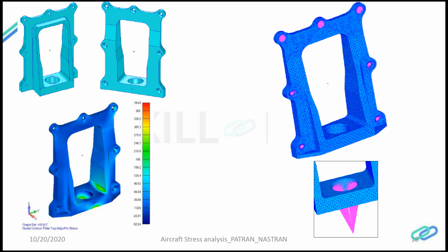These bolt locations have been modeled using spider elements, which is RBE2, and finally this is the lug hole or the pinhole that attaches this lower fitting of the galley to the aircraft floor structure. That is again modeled using RBE2, and then I extracted the loads.